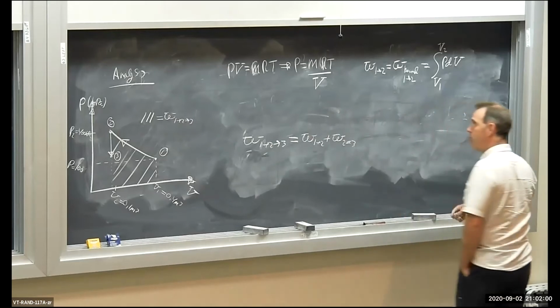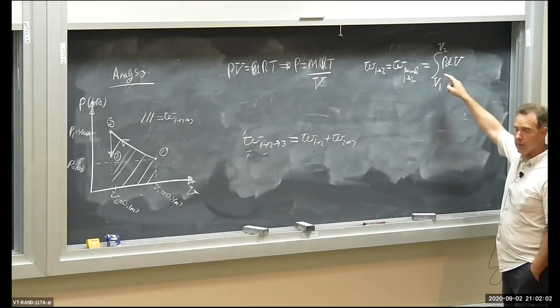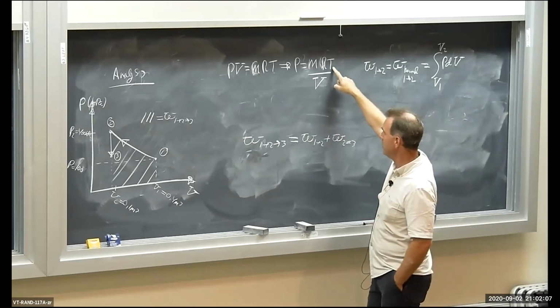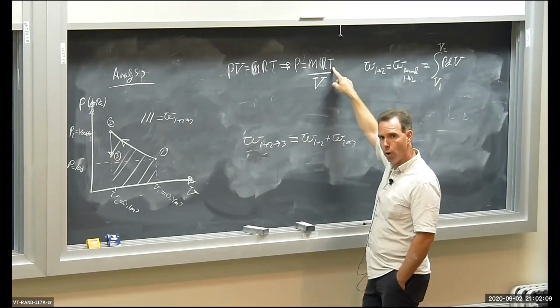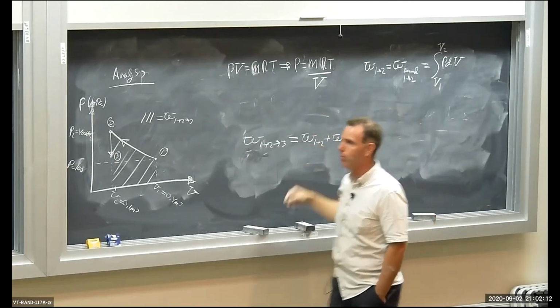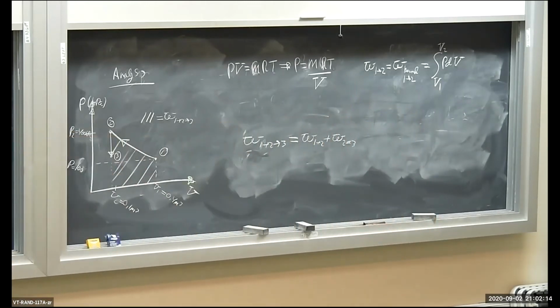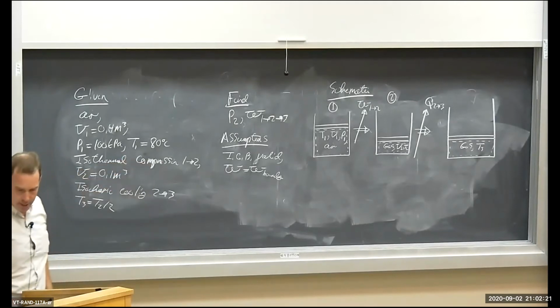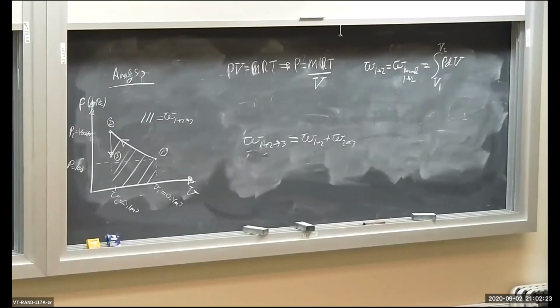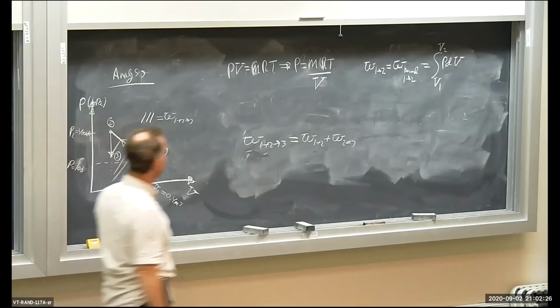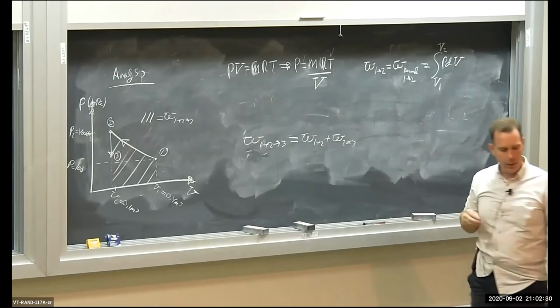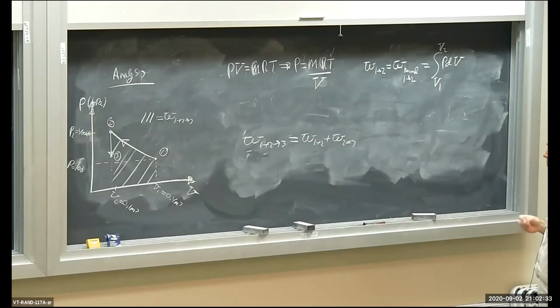Now, I could substitute that into this integral here. The only little thing is, I know what temperature is. How do I know what temperature is over the process 1 to 2? It's an isothermal process, and I get a temperature of 80 degrees C over here. So here's temperature T1, just convert that into Kelvin, and I could immediately plug it into the ideal gas law. So I do know the temperature. The gas constant, I could get it if I wanted, fine.